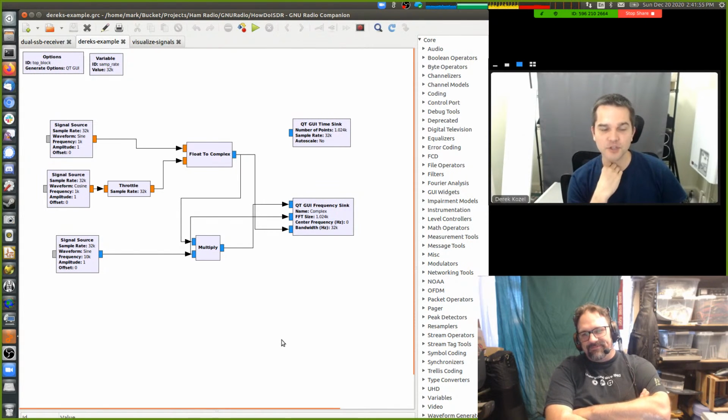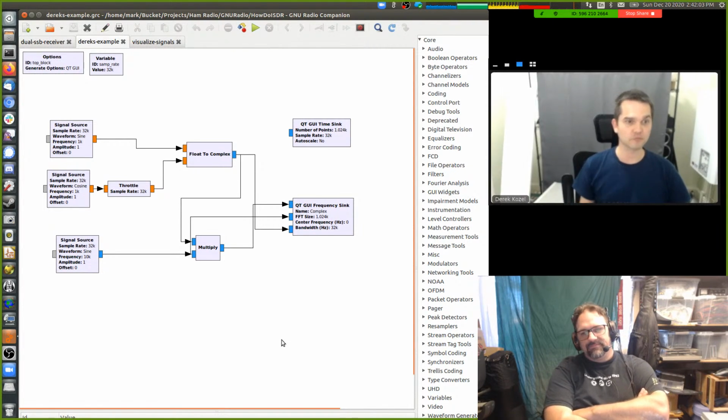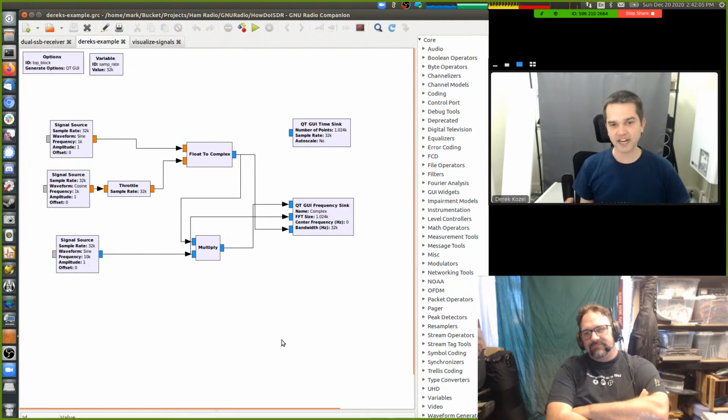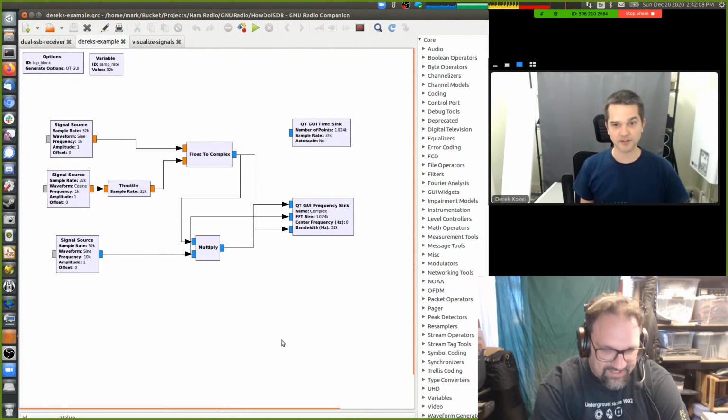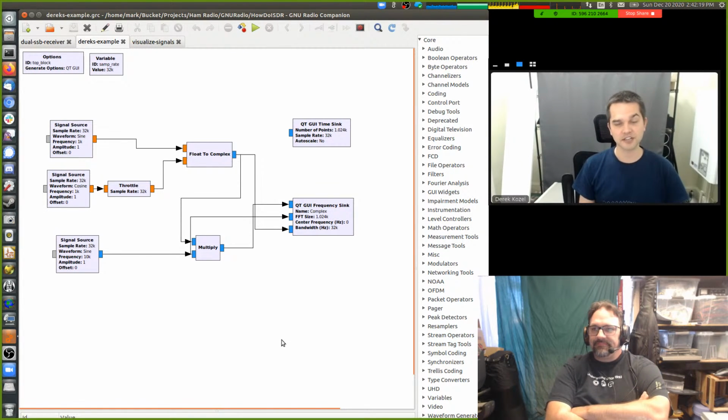Yeah. So if you're adding phase every sample, then it'll be rotating in one direction. If you subtract phase every sample, yes, that I get. It'll rotate in the other direction. And this is the difference between a positive and a negative frequency. It's a negative rate of phase change or a positive rate of phase change. And you can't represent that with just a real signal. You need complex numbers to show negative phase change.